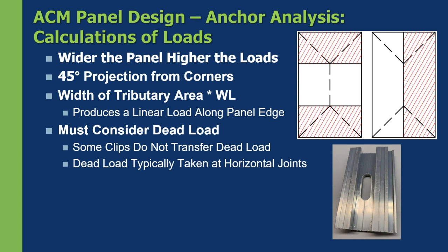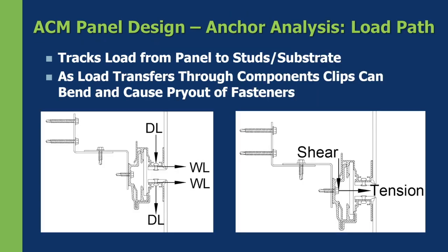That slotted connection is not going to allow for the transfer of dead load from the vertical panel edge to the Z-girt, or whatever girt you have behind there, which means all of the dead load is going to be taken only at the horizontal joints. This is very important for your engineers to know. Be courteous and detail it clearly in your shop drawings.